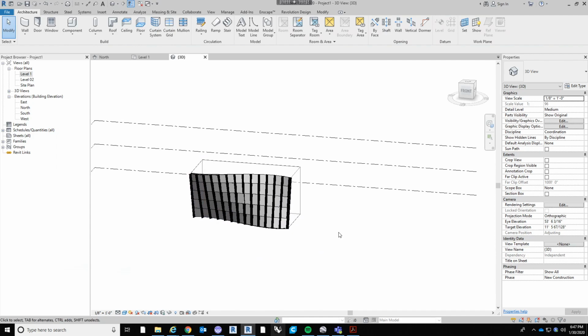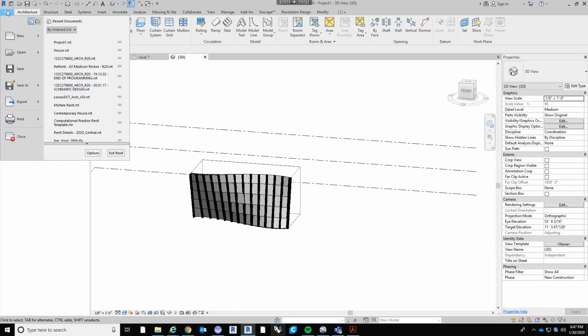Guys, when Garrett says open up your template, he means open the template through Revit, through a project in Revit. Don't open it as a template to be manipulated, because you can only save templates. You can't save projects.